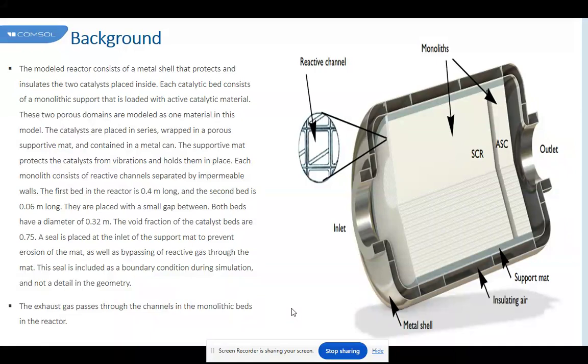For transient operation where the time to light-off is important, it is shown that for the case of back-end ignition, corresponding to low inlet temperatures or low catalyst loading, metallic substrates are again superior. However, for the case of front-end ignition, ceramic converters may lead to lower cumulative emissions at lower inlet gas velocities, while the converse is true at higher velocities.